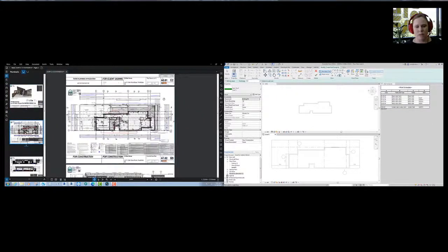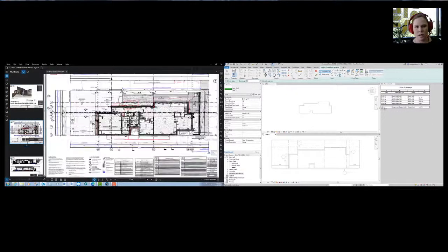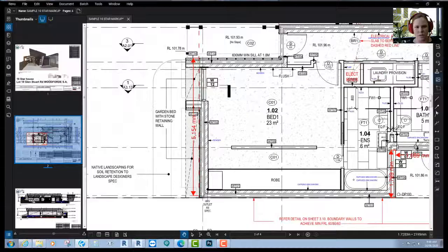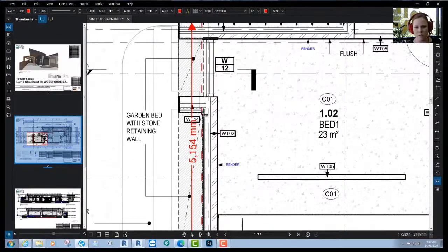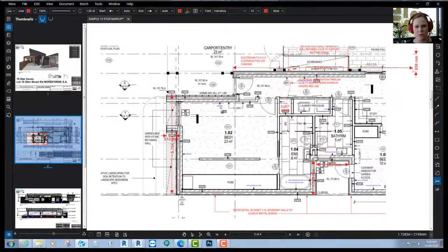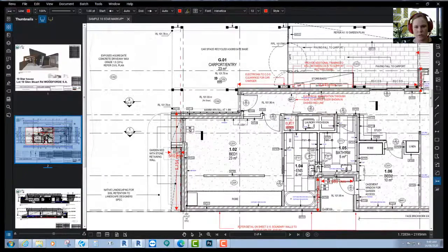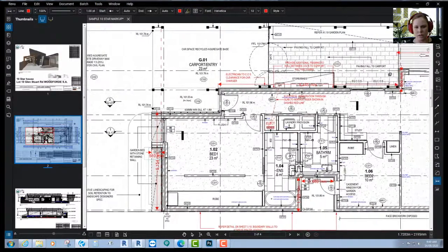So the parts that I'm starting to look at here are particularly around the west and the north face, because we have an overhang on this building. So we have a slight overhang on the eave on the front. We've got some wing walls that shade that western window as well. We also used Revit to have a look at the daylighting to see what sort of angle they needed to be at. Which is why we've got such a striking front on the front of this 10-star house.